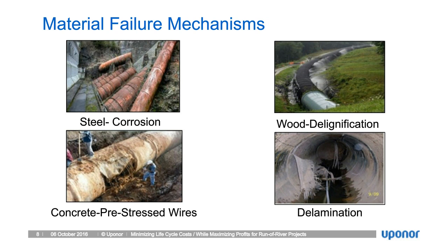Wood delignification: as I said, if wood is completely saturated, it actually resists a lot of degradation. But when you have to shut it down for inspection and the wood dries out, it causes delignification. Also, because it is wet, the environmental aspect is that you'll get mold or moss growing on top of it, which then accelerates the delignification of the wood.